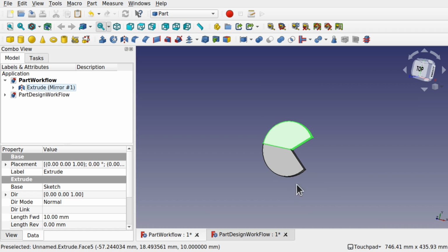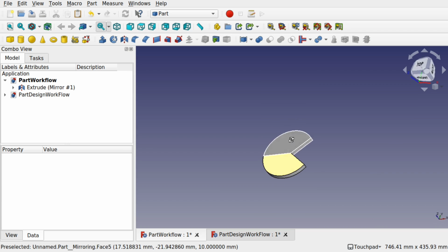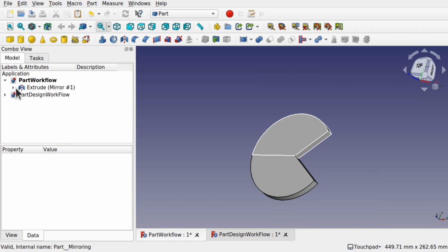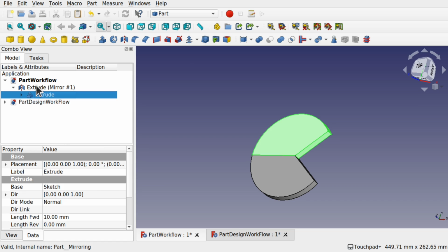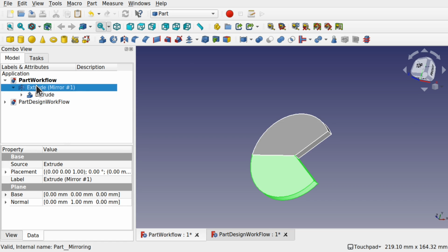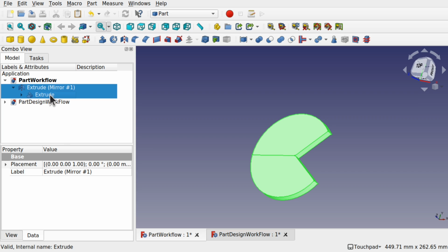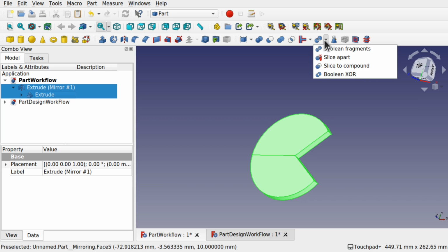And it's mirrored across like so. So we've got that there. There are two separate parts in there. That mirror's there. We can't refine that at the moment. The way to refine it is to take these two. So refinement's getting rid of this line here to create one face, so like and like faces connected together. We'll make a Boolean across that.